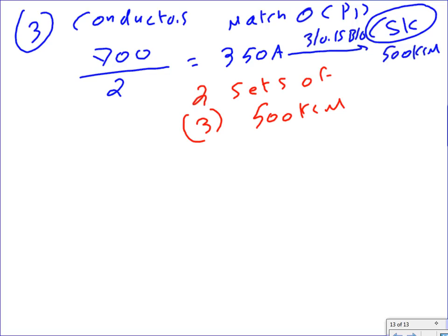Since it's lights and since it's harmonics, I know it's 800 amp and big. I made a decision to pull a full neutral. I can't derate the neutral here. I made a decision to pull what? A full neutral. So that will be what? 2 sets, guys, of 4 conductors. Why 4? 3 phase and neutral. 2 sets of 4 conductors, 500 kcmil each.